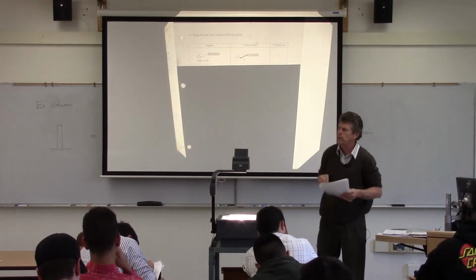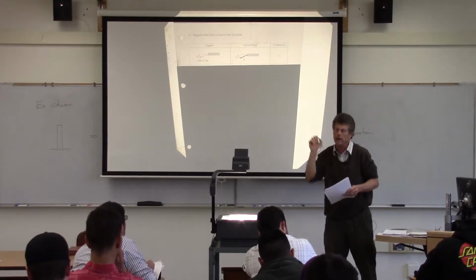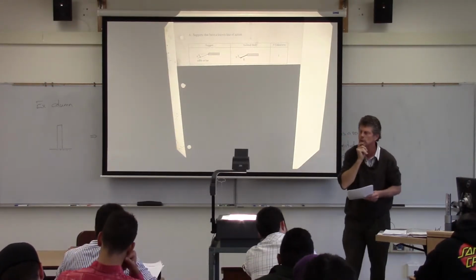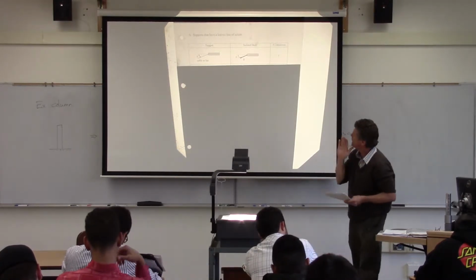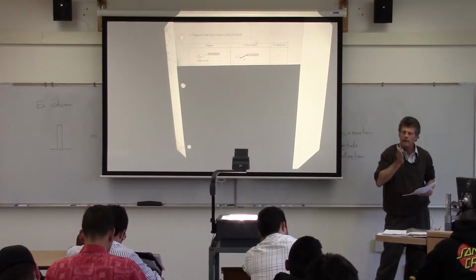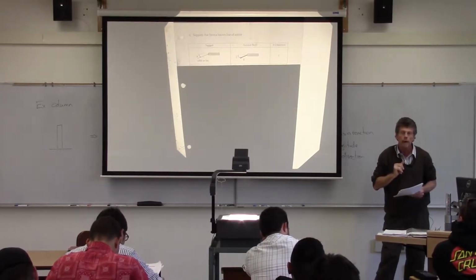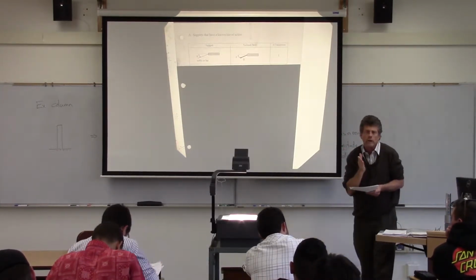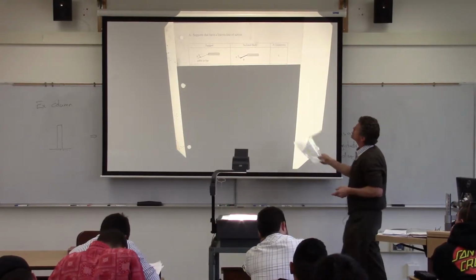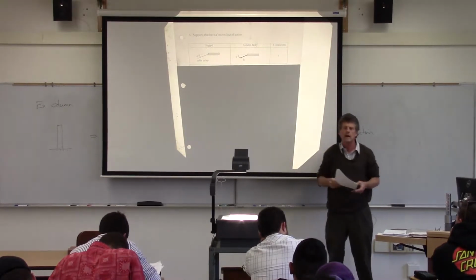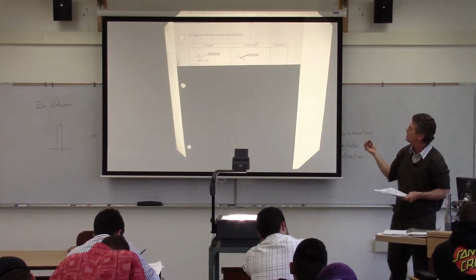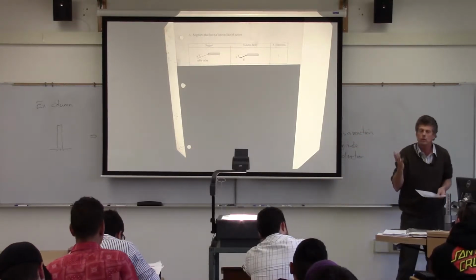And think about it. The cable's probably pulling on it like that. Maybe not. I don't know. But it may be pulling on it. So we're going to substitute what we think is going to be the force. But the nice thing about that is that we know its direction. If I can measure the cable and its angle of incidence there on the body, then basically my force has to go that way. A cable can't apply sideways forces and that sort of thing. So the nice thing about that then is I'm down to one unknown.